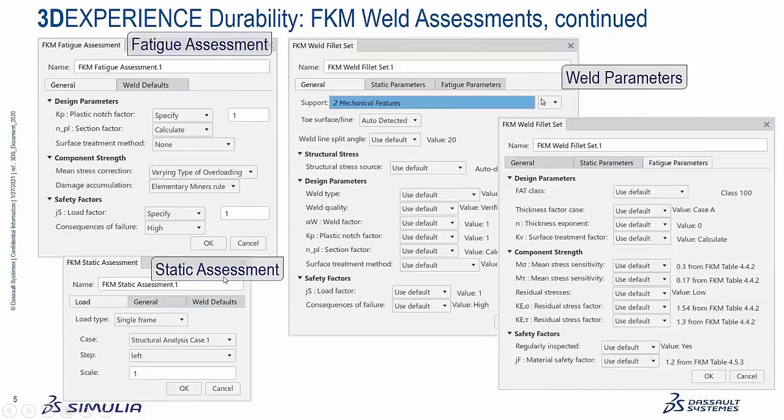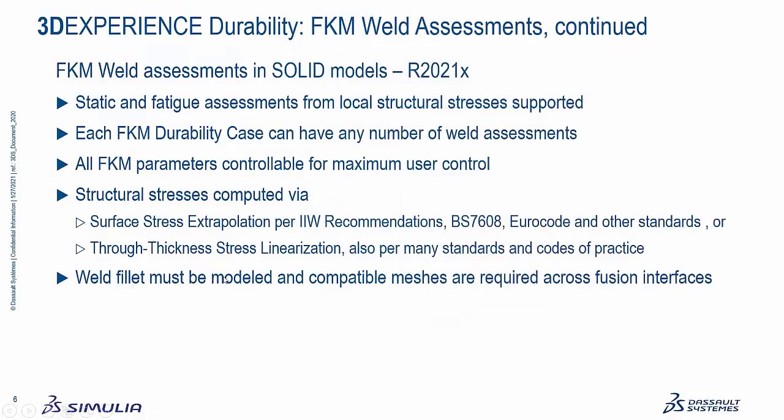So just a summary, just a reminder, this only applies to solid models at this point. Static and fatigue assessments here. We use the local structural stress approach. We do not use the nominal stress approach.